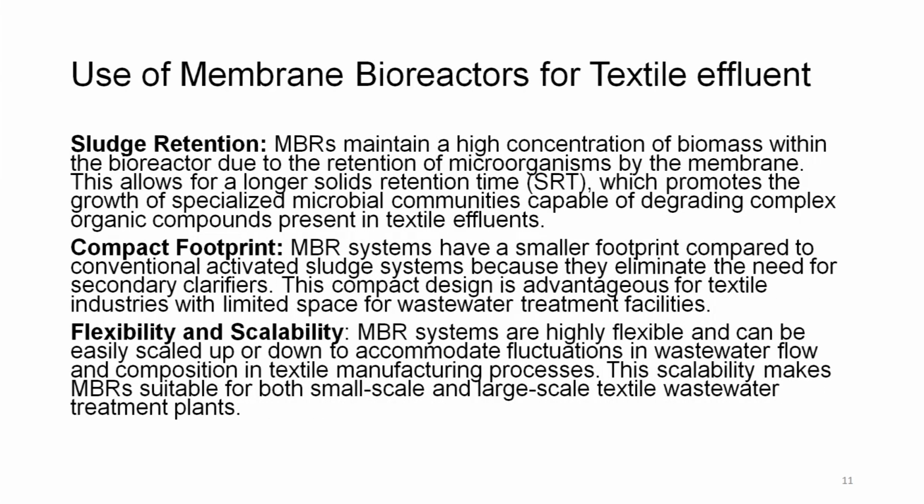Sludge retention. MBRs maintain a high concentration of biomass within the bioreactors due to the retention of microorganisms by the membrane. This allows for a longer solid retention time, SRT, which promotes the growth of specialized microbial communities capable of degrading complex organic compounds present in the textile effluent.